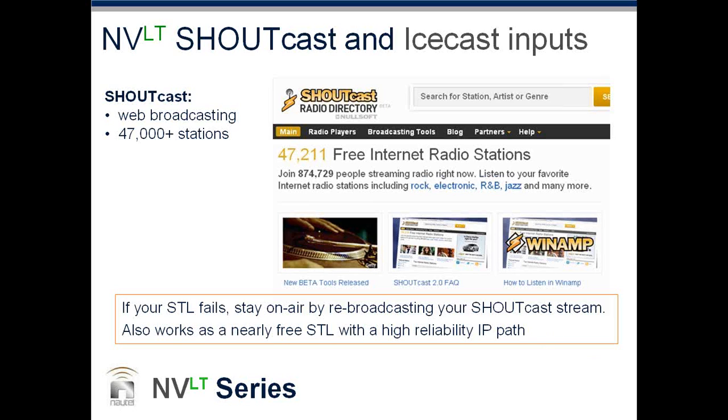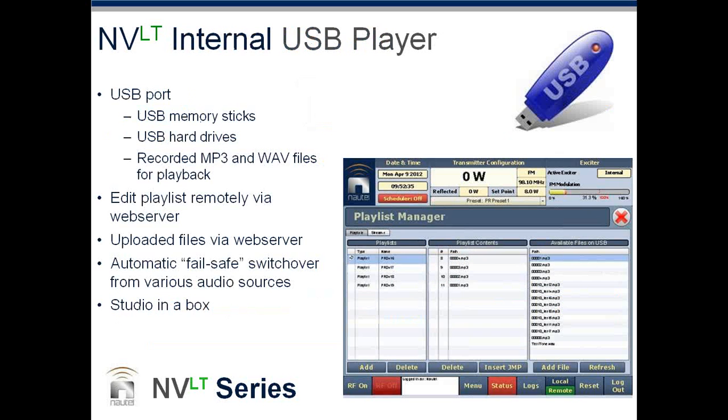Shoutcast, Icecast, the ability for the transmitter to know that you're streaming, and if the main STL were to go down, the transmitter can be instructed to automatically switch over to your web stream and pull up that web stream and put it on the air. Very, very powerful. It also could be a nearly full STL if you have a high reliability IP path.